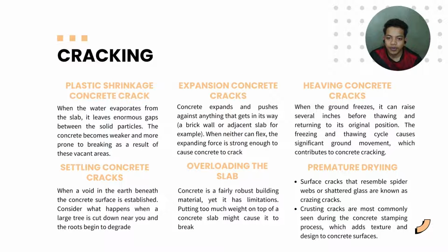Plastic shrinkage concrete cracks happen when the water evaporates from the slab. It leaves enormous gaps between the solid particles. The concrete becomes weaker and more prone to breaking as a result of these weakened areas.